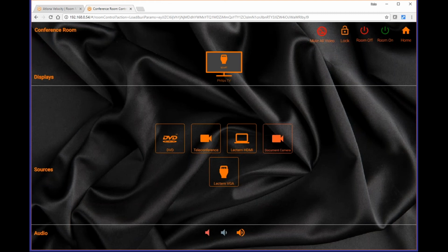That basically switches all devices that are in that room. So if you have a projector and a television and a DVD player, it's like an automated macro that runs in the background. You can exclude or include any of the devices in the on and off macro. There is also a wait timer you can define. If you have high power consuming devices like a video wall, you don't want to switch them all at the same moment, but you can have like a 1 or 2 second delay in between.